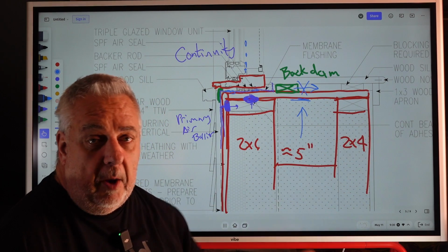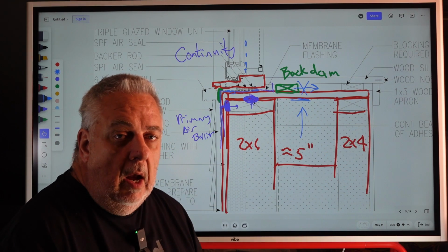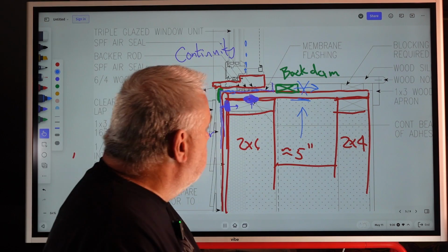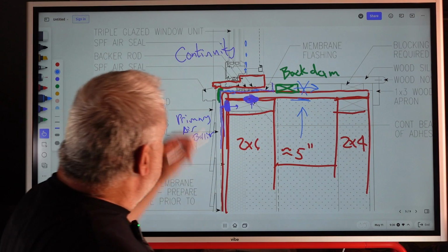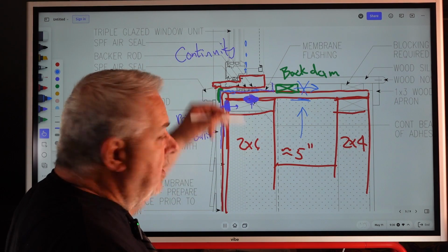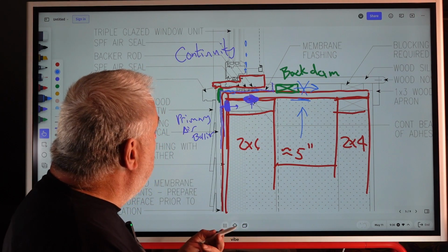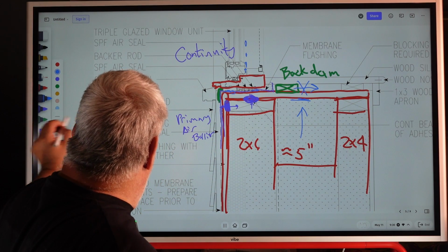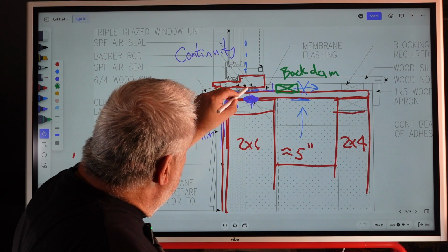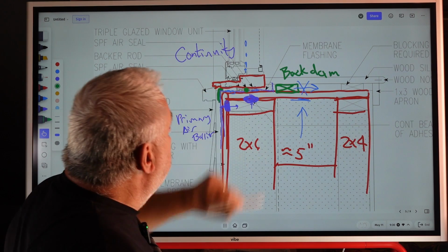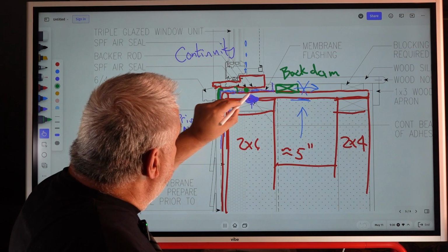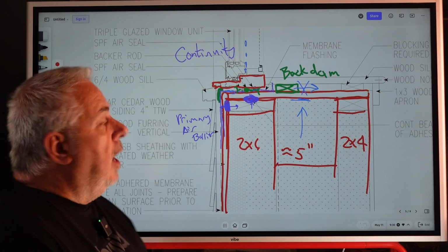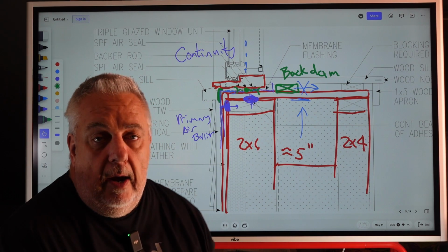It's at the right temperature. You got water activity and the food source, the paper-backed gypsum board. It's a great food source for mold. So anyways, windows, they get installed, plumb, all of that stuff. And then notice we would put a backer rod, we called for it, there, and then we would put a bead there and or expanding foam on both sides of that.